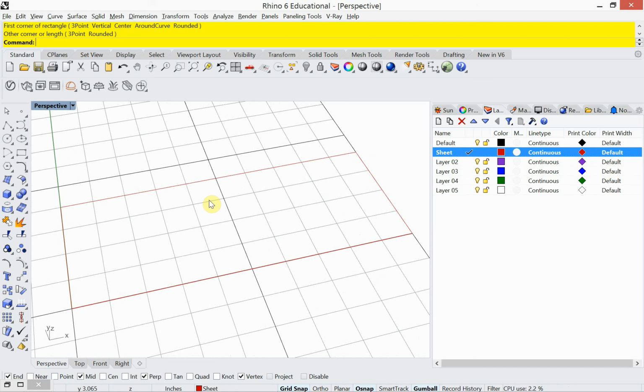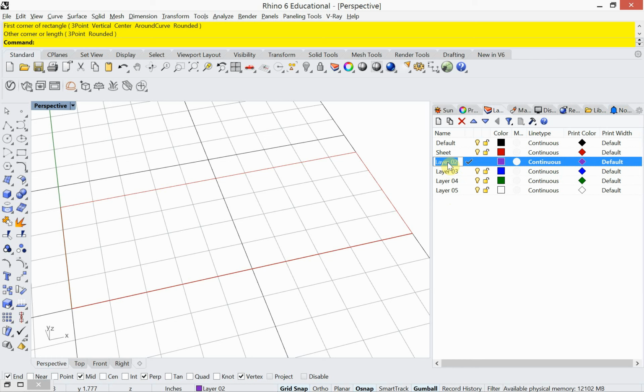Okay, something else that's really important, I think, when you're creating your 3D models is your layer structure and how you set that up. And that can be based on building geometry, that could be based on Rhino geometry, and today I'm going to look specifically at using this layer setup and how it relates to Rhino geometry. So everything that you draw two-dimensionally is actually a curve in Rhino. So I'm using the abbreviation CRV for my curves. Eventually I'll have surfaces, but I'm going to start with curves, so I'll make that current.